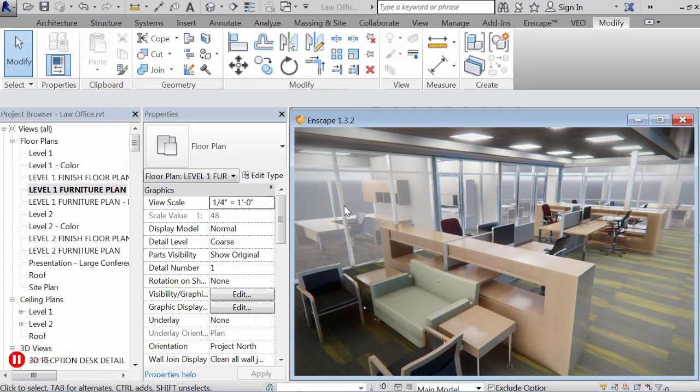You guys have just done a fantastic job here, an incredible level of detail. But from what I've read, this is not something that you would consider out of the ordinary. This is what's possible every day. Correct. There are pretty simple workflows, like I mentioned. Once you get things set up in your template and you have a precedence for those thin floors, drawing a finished floor is pretty much the same amount of work as drawing a filled region.